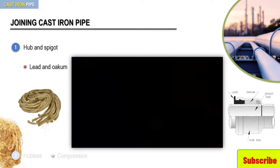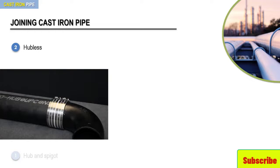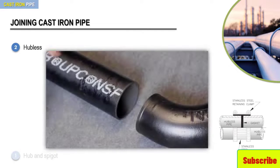The next group is the hubless cast iron pipe. Hubless cast iron pipe uses pipe and fittings manufactured without a hub, as in this example. The method of joining these pipe and fittings uses a hubless coupling that slips over the plain ends of the pipe and fittings and is tightened to seal the ends, as depicted here. The following video shows a simplified installation procedure.